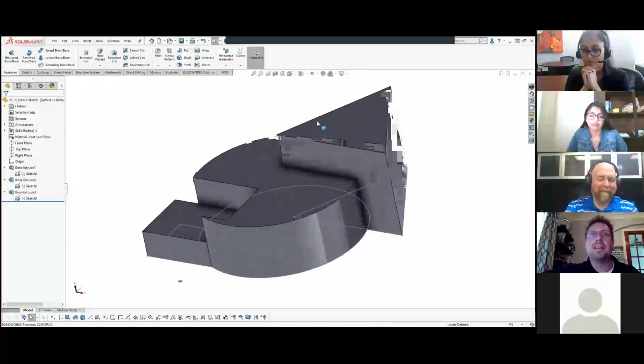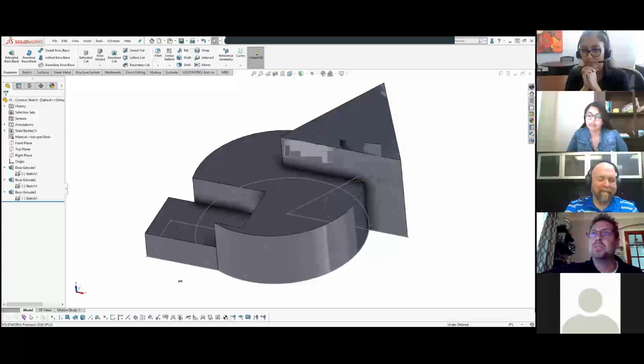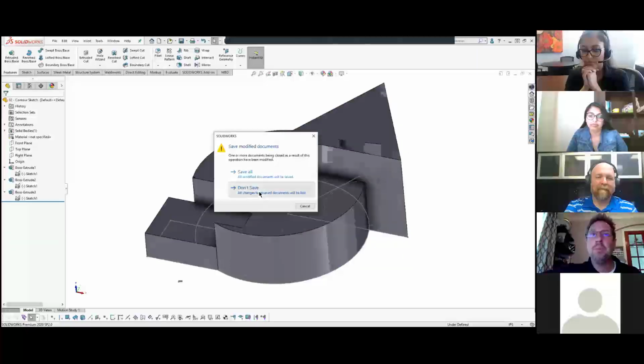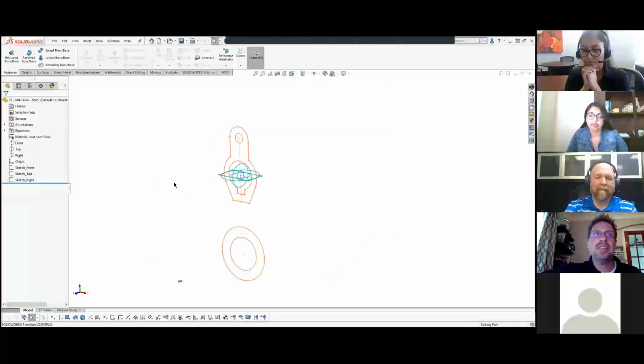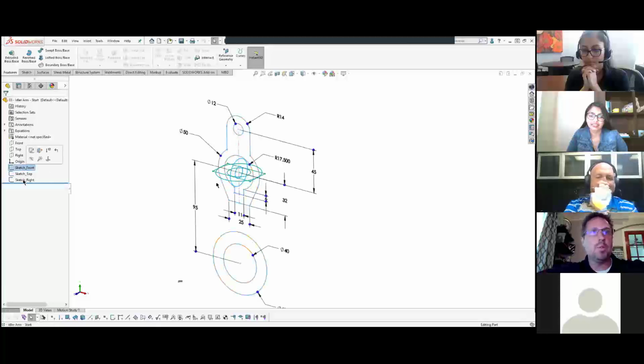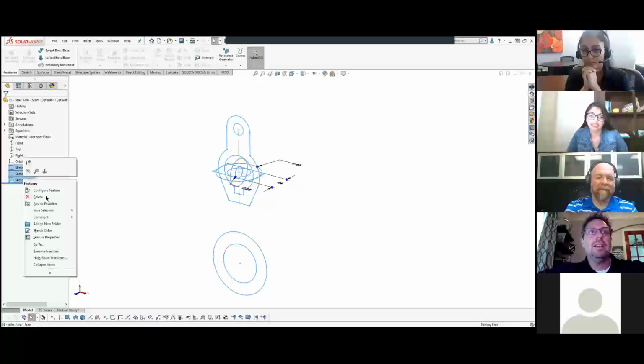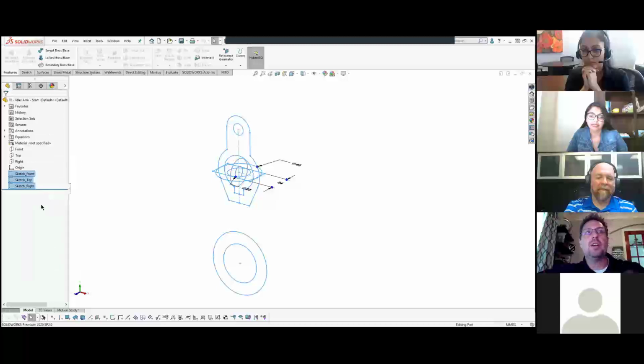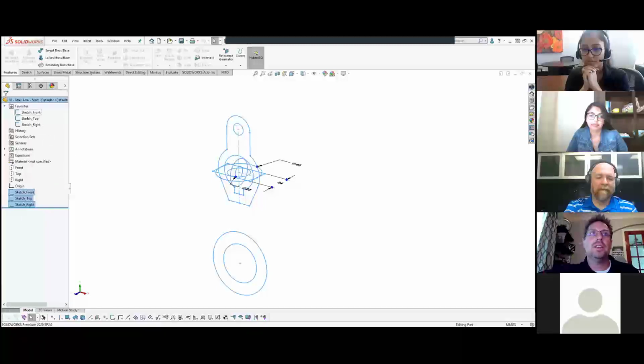So try to minimize the number of steps you can do with a single sketch, and try not to make those too complicated. But if you have three different sketches, if anybody has been in the Essentials class, you can go through this example. I'm going to do one more thing. I do like adding things to favorites. If you're going to go back and forth to the sketches, it puts them in a little favorites folder, and then you can see all your sketch favorites here.